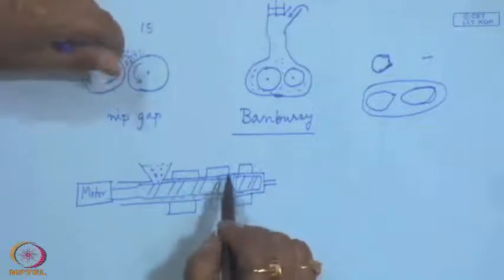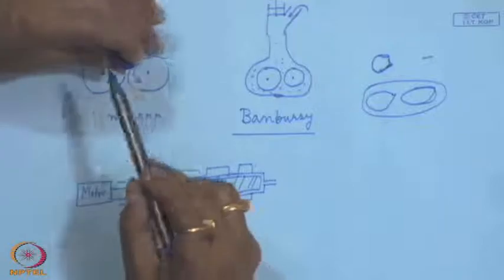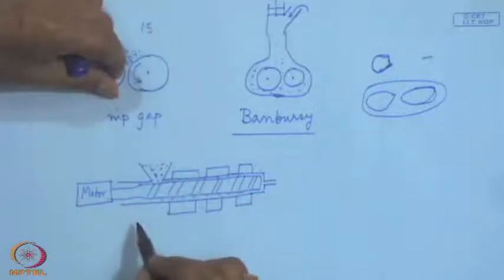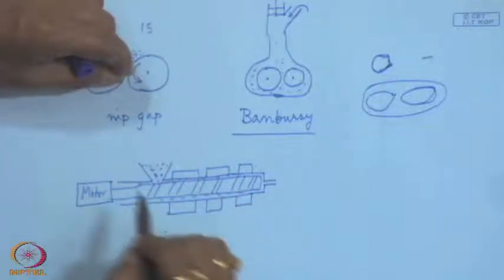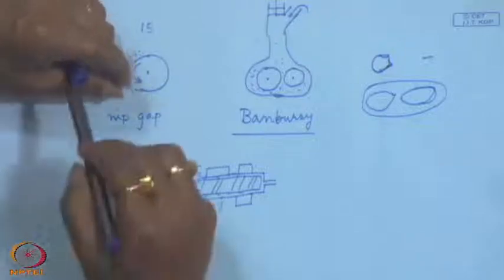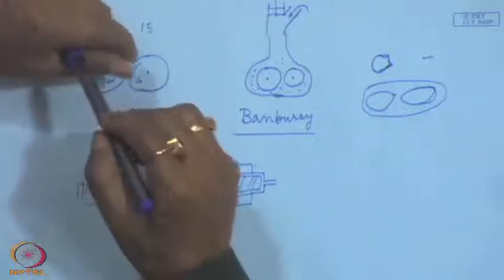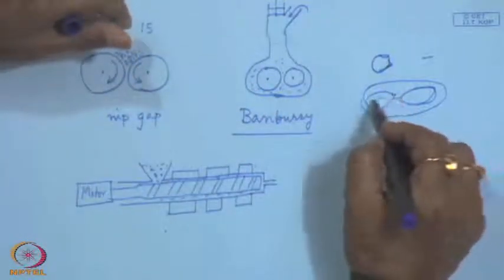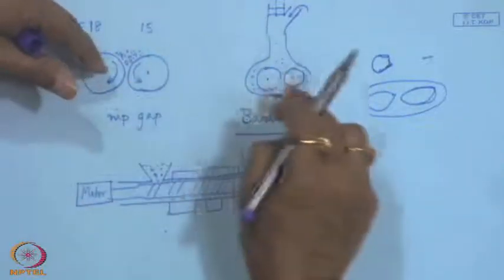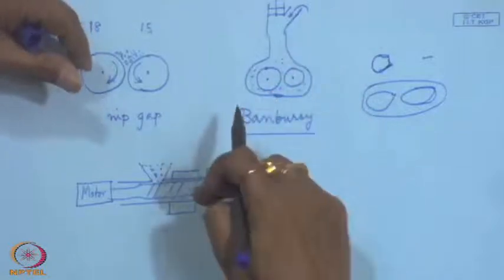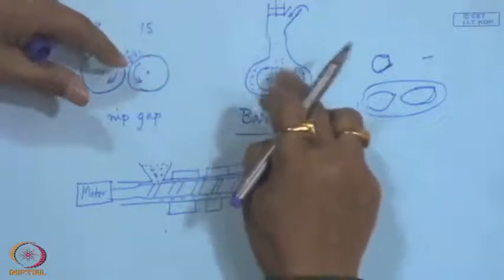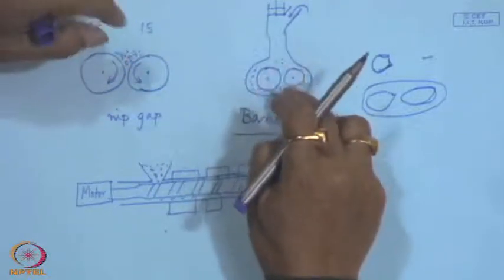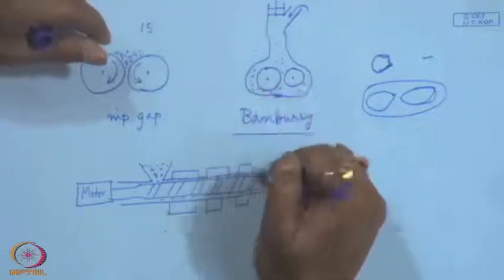This is also a technique for manufacturing say pipes, tubes or coating of wires, etc. Also it is used for blending of the component polymers. This extruder can be a single screw extruder or there can be a twin screw extruder within the same barrel. So, twin screw extruder is a kind of modification of the open two roll mill, or again of the internal mixer, in a continuous way.